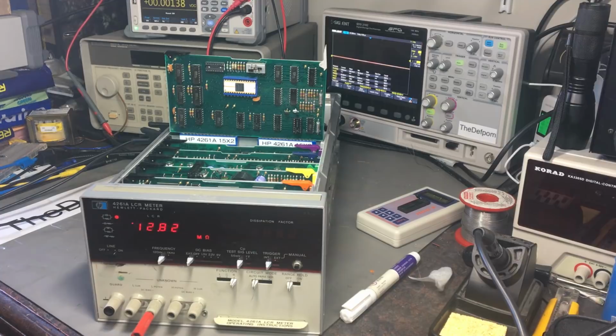So what it's looking for is logic levels being observed at TP3 and U15 pin 9, TP4 and U15 pin 4, TP5 and U15 pin 7, respectively, when the LSC 0 signal is at high level.